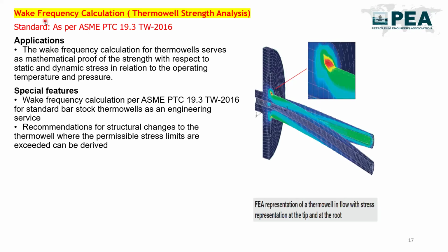Now there is one very important point for the thermowell. When you are going to select the thermowell, the strength analysis calculation is very important, because the thermowell is directly inserted inside the nozzle of the pipe, and it will experience velocity, density, viscosity, temperature and pressure inside the pipe. So its strength needs to be checked while we are designing this thermowell.